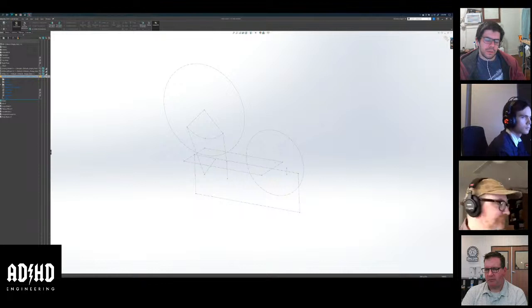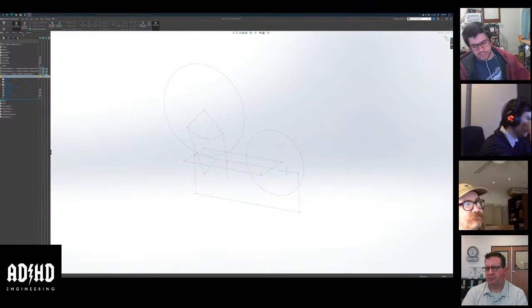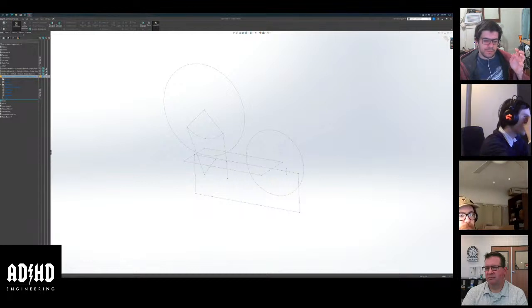Andre. Yeah. Skeleton, so what I'm thinking about is the vibraphone assembly, right? That thing's tilted at an angle, but it would be convenient if the subassembly, or whatever that ends up being in the SolidWorks form, is all at right angles, because then you can do your patterns better, and then you just take the entire block and shift it. So I don't know if that means the part... Yeah, the subassembly. That's a good argument to have every part or component or subassembly have its own origin. And honestly, there are good arguments for that, and I think that's one of them.